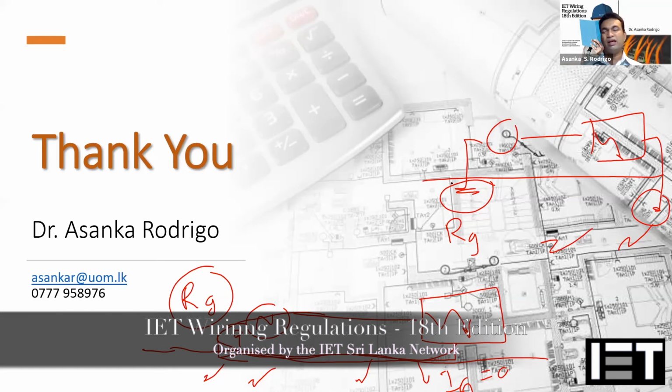I cannot say a value, because that will depend on the different manufacturers and their driver circuits. Some manufacturers handle the harmonics depending on the PWM signal or whatever the switching frequency is. There are also some low quality drivers which can create higher leakage currents. So that can vary depending on the type of driver, and because of that I cannot give an exact value or say this is the typical leakage value. That will depend on the driver circuit.